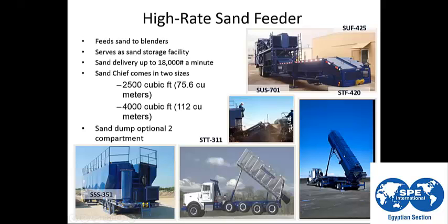With the same function, this sand silo is used instead of using sheaves to transport the sand from the hopper at the sand silo to the hopper of the blender. We can use this to avoid any mechanical parts. Just with gravity, we can connect this truck to the blender to avoid any failures during the job due to mechanical moving parts.